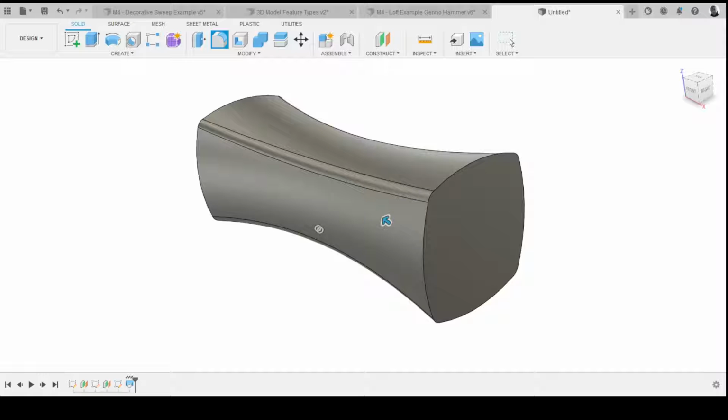So the way I approach this fillet, because I want to fillet this side as well, if you select these lines first, this will make a nice curved shape, and you'll select it in one go. Whereas if you've got hard corners between where those fillets are, you have to select each line you want to fillet, if that makes sense. So bear that in mind when you're filleting. It might be simplest just to fillet faces in this instance, but it's worth bearing in mind, that's one way of approaching it.